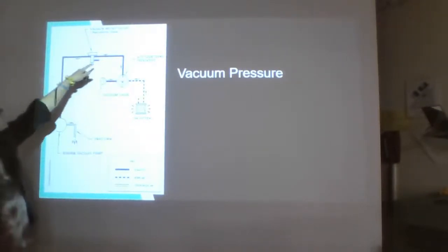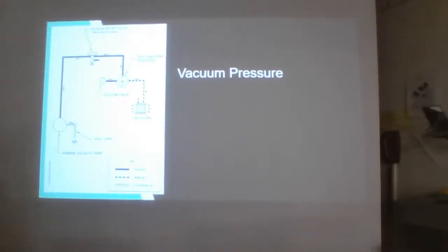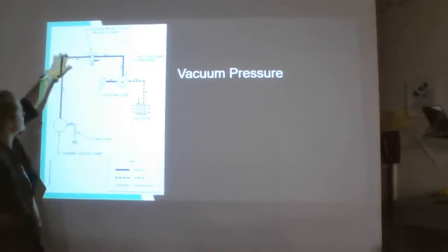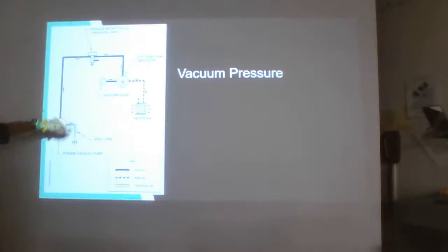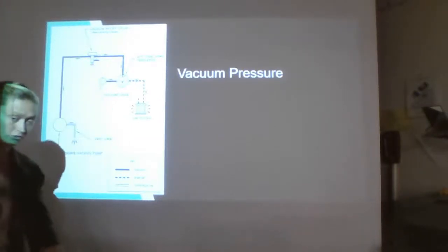And we have our air that's sent to our relief valve. If the pressure is correct, then the relief valve stays in place, and it goes around and around, through the vacuum pump and back. And if the pressure ever reaches above what it's set for, then that relief valve will relieve the air.